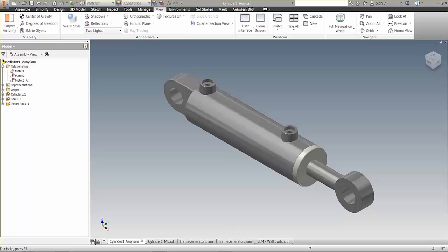This hydraulic ram was created as a part with 3 separate bodies, then exploded into individual parts and dropped into an assembly. Inventor has a tool which performs this in one single command, no matter how many bodies exist in the part. The 3 individual bodies, in this case the cylinder, the seal, and the piston rod, were all detailed individually, adding features like edge radius, groove detailing, and material definitions.